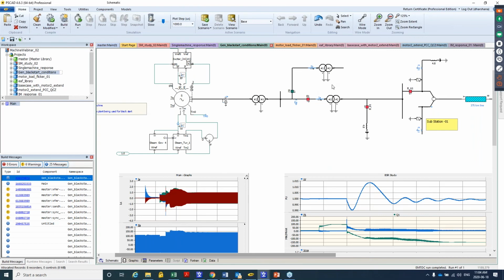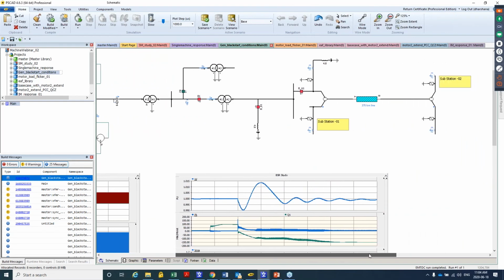Then you may also want to start studying, okay, can I energize the second parallel unit without causing sympathetic inrush, right? Then energize reactors and so on. But an important point is, can I also energize a long transmission line to go to my loads or go to my next generating station where I can connect 2 generators and then keep on energizing the rest of the system.